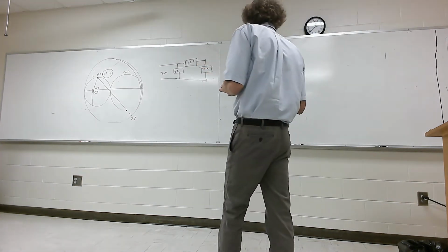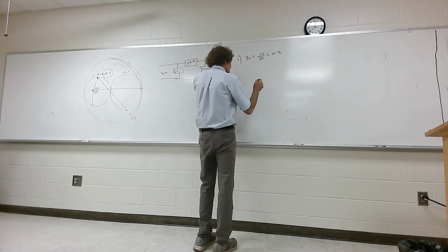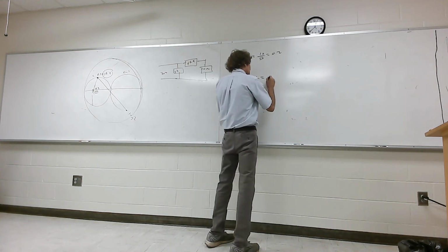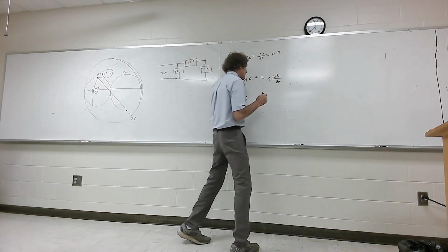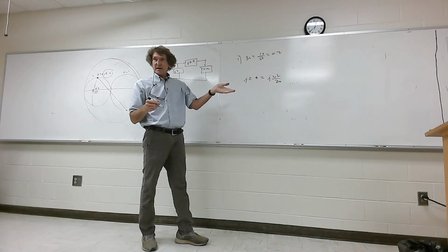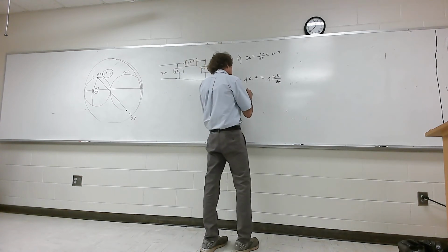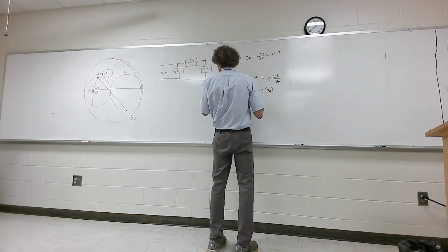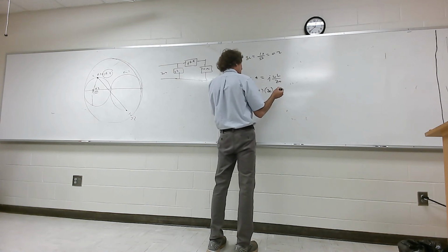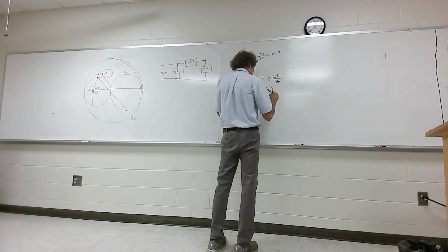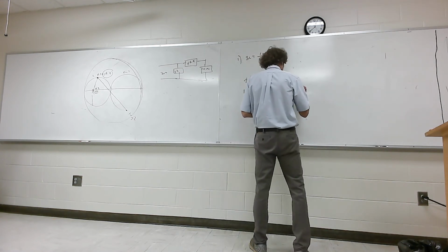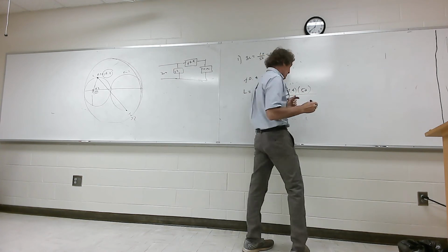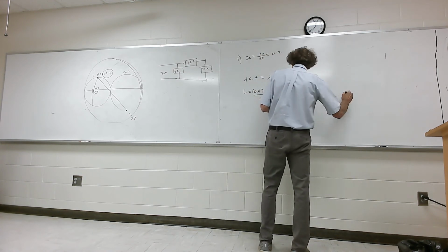That's it. Alright, so for this one, this is an inductor, we had J0.4 equal to the normalized inductive reactance, right? That would be J omega L over Z naught. I put down the formula just so you see. I want L. So L itself is equal to 0.4 times Z naught. Z naught is 50, I think. Then it's divided by omega, correct? So I have 0.4 times 50, and then it's divided by 2 pi times, at 1 gigahertz, 10 to the 9. So give me the value of L first.